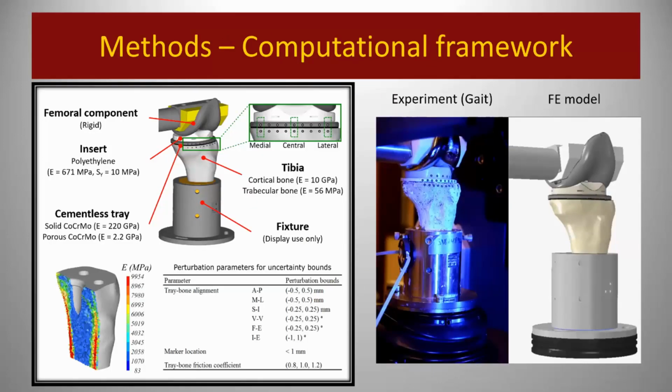Finite element models of the tibia were developed in Abaqus from CT scans. Elastic properties of the tibial elements were assigned based on Hounsfield units using established relationships and calibrated with bone mineral density phantom. Implant alignments were reconstructed and calibrated by using surface models of the bone and tray obtained from DIC and Optical Strain System.